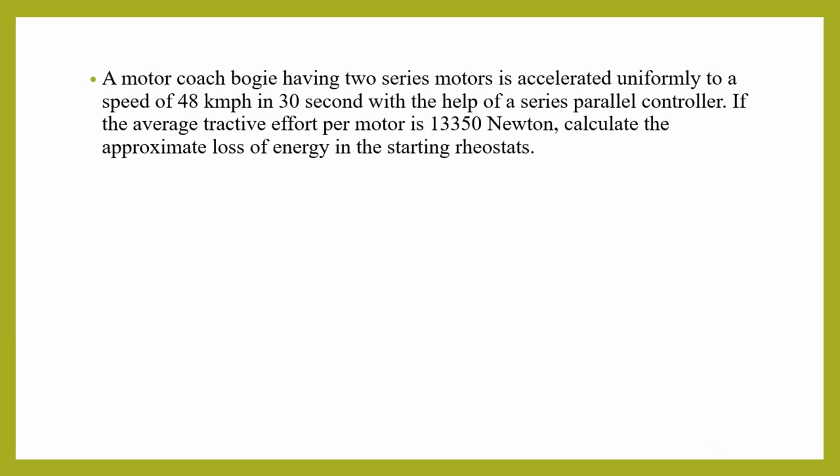Let us see the problems related to series parallel starting. First problem: a motor coach bogie having two series motors is accelerated uniformly to a speed of 48 km per hour in 30 seconds with the help of a series parallel controller. If the average tractive effort per motor is 13,350 newtons, calculate the approximate loss of energy in the starting rheostats.